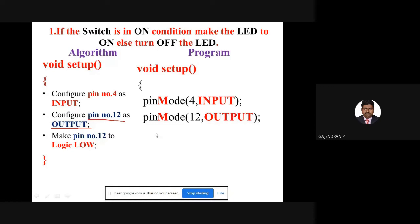So immediately I need to make the particular output as low. So low means digital write 12, low. Is it okay for everyone? So void setup only 3 lines. Configure the pins and also make the output remain as an off condition. Here off condition in our state is low. So digital write 12, low.